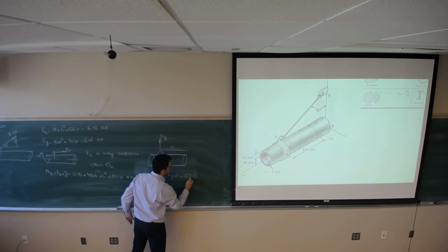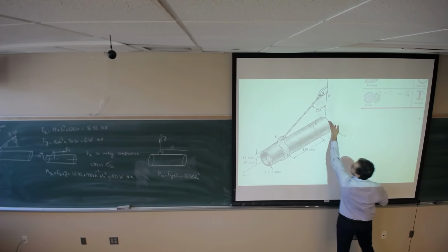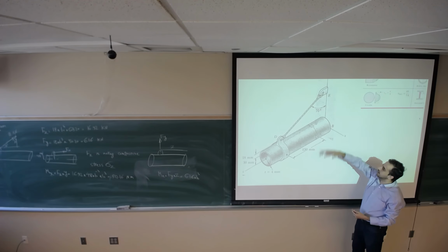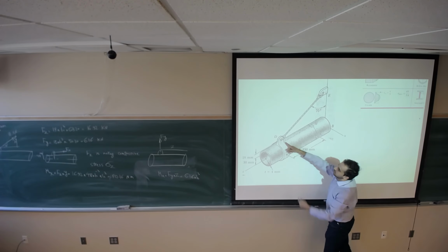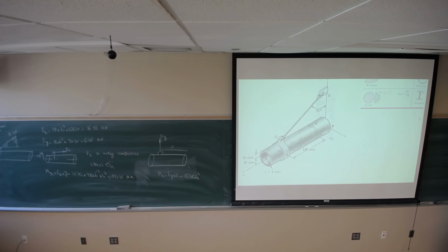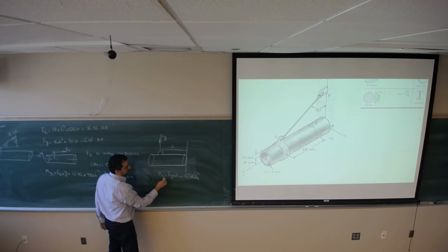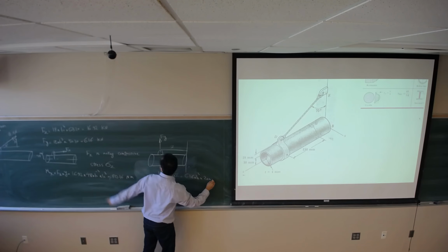So Fy is 6.16. This section has the longest distance from point D in the z direction. Can you see that? So basically, based on this force, this section is going to see the maximum bending moment. So Mx max is going to be 6.16 times 200.